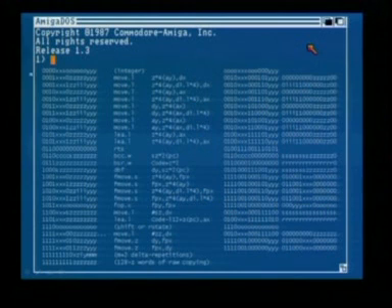So you need to have some kind of integer operation. Here on the left-hand side is the encoded instruction format that is used internally. There's the instruction here where the letters correspond to the fields out here. And then there's the decoded form, which is how the instruction is normally represented. So you can see that all of these instructions are usually quite a lot bigger in the normal format than in the compressed format.